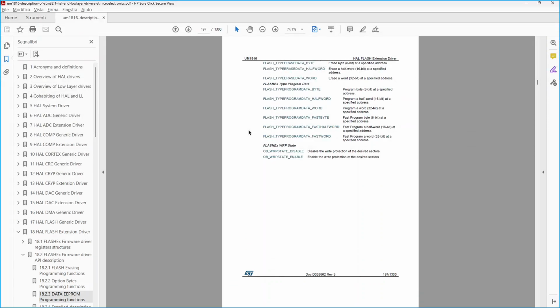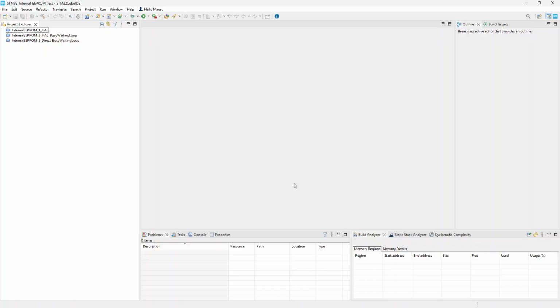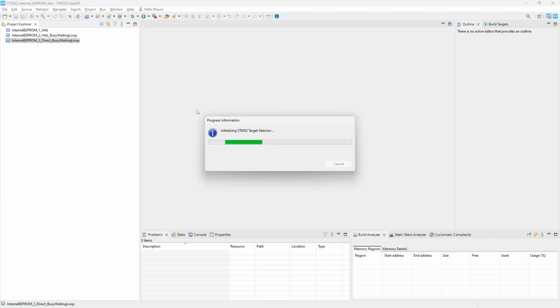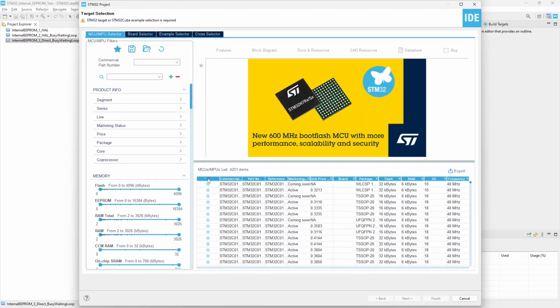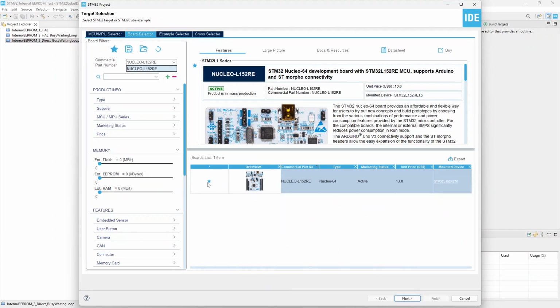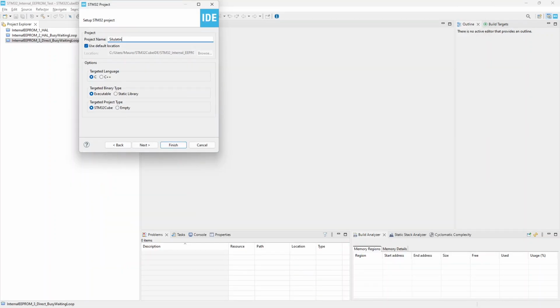Having these features, as per the microcontroller documentation, I prepared a series of tests measuring timing and results over various EEPROM operations. The same tests are repeated in 3 different projects, implementing tests in different ways, but all of them having the same CubeMX configuration I show you here now. Projects have just the default Nucleo board configuration, as the device to test is internal to the microcontroller.